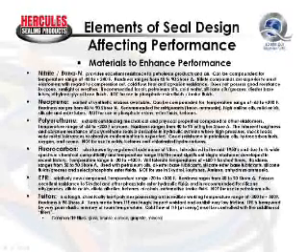Ethylene propylene has a temperature range of minus 20 to 300, hardness from 40 to 90 shore A, excellent resistance to Skydrol and other phosphate ester fluids. So that would be the principal reason you'd use EPR, is because of its compatibility with a wide range of phosphate ester fluids.